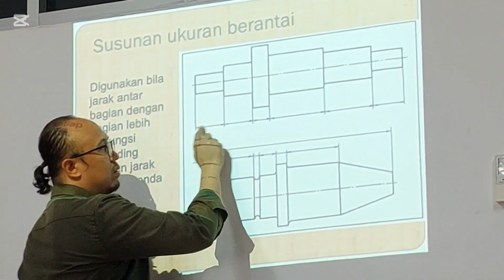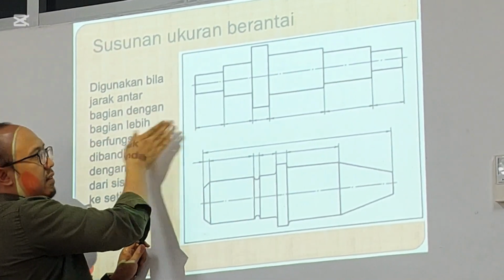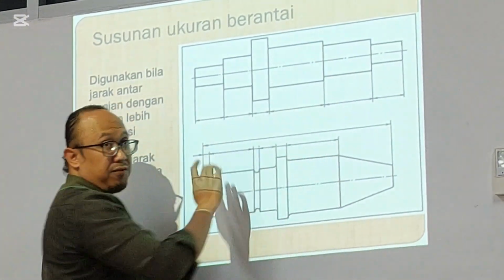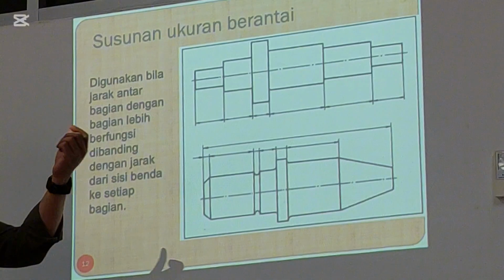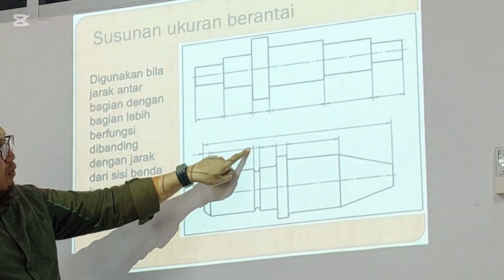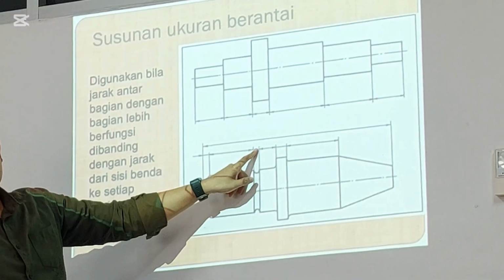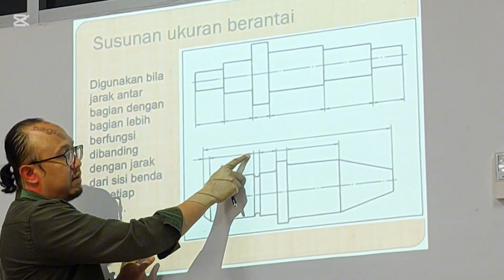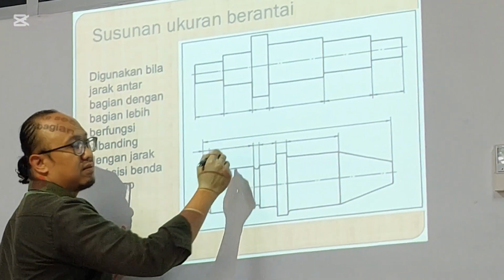And then you can use the same line, but give the arrow pointing sometimes to the left side, right side. It means that this plane is mentioned in this area. But if some area is too small, there is no need to add an arrow. Just give a slash, it's also okay. If you're facing a small area like this, this arrow and this arrow belong to this area. This arrow belongs to this area. But if you want to put an arrow in here, it's not enough space. So you can simply not add any arrow because it is already represented by this arrow. So this area needs no arrow, or we can add a slash or dot. It's also okay.